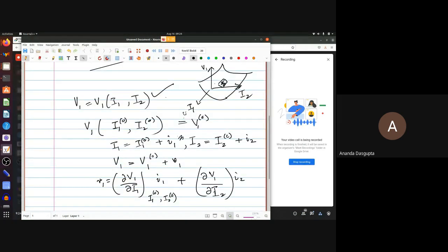By the way, when I say AC, please don't imagine immediately that you get a sinusoidal variation like you see in your AC chapters in your textbook. Here, AC means any fluctuation from the DC value. Well, the name AC is fine because if DC is your average, then the fluctuation has to be both positive and negative, right? Because the fluctuation has to average to zero. So in that sense, it's AC. But it's not necessarily a nice sinusoidal signal. Often it is, but it doesn't have to.